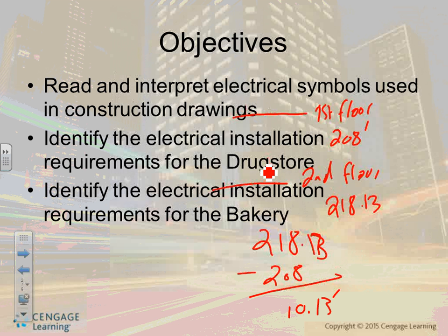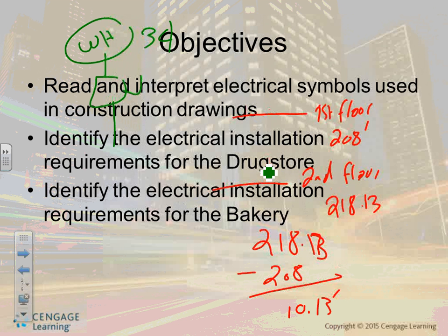So there are 3 circuits, 3-phase. It's a 3-pole circuit breaker for this circuit. You guys following? So here's my disconnect, here's my water heater. It's a 3-phase water heater.